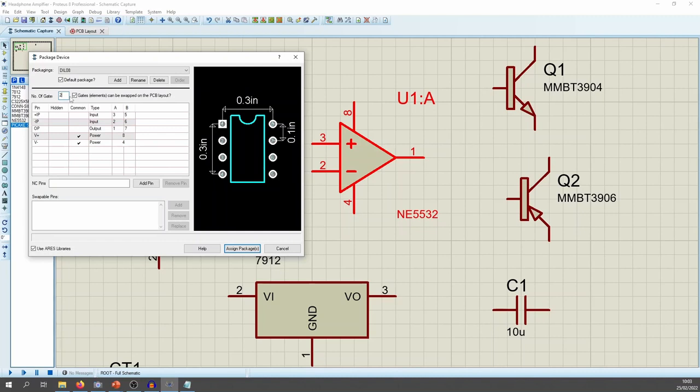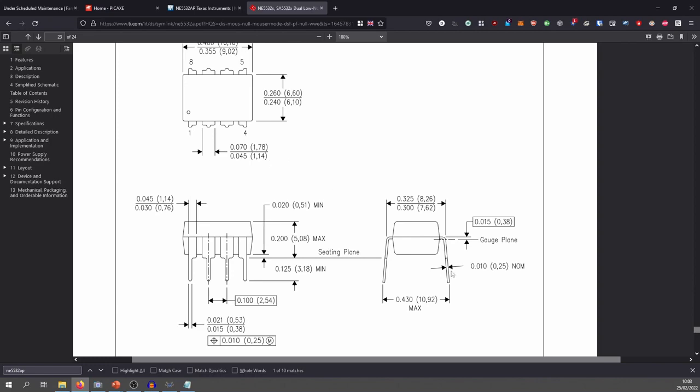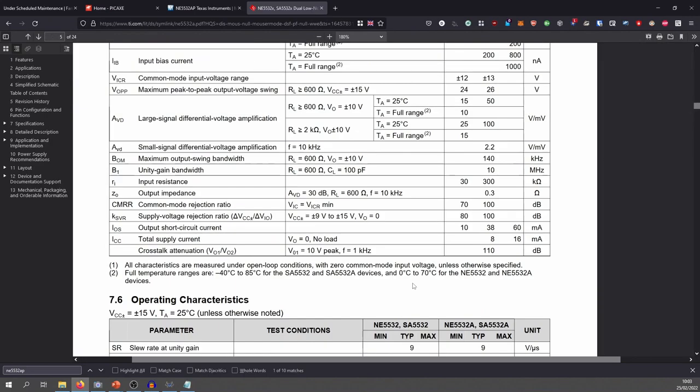They just call them gates. Could be all gates, could be op amps, could be whatever. There's 2 of them. A and B denote the different columns for each op amp. And then you see that the V plus and V minus of this number spans all of the gates. That's because this common thing's checked. When you click common, it means that that pin applies to all gates.